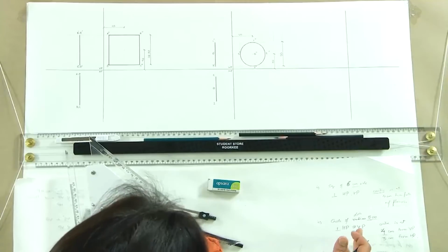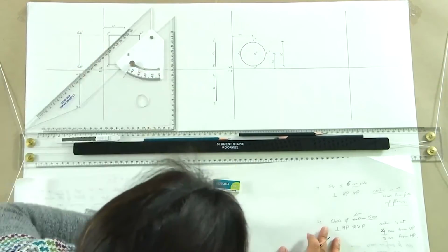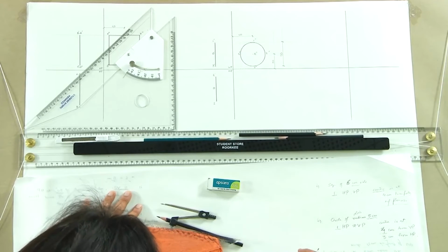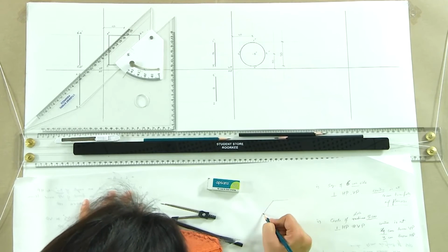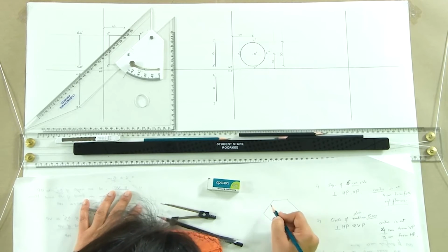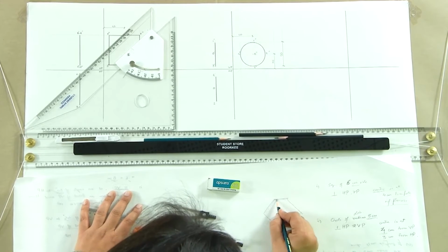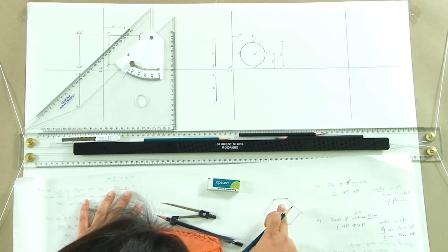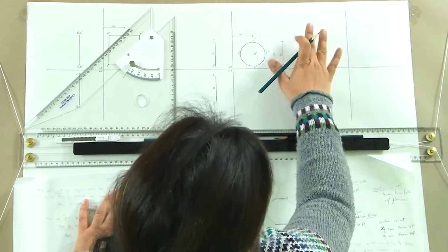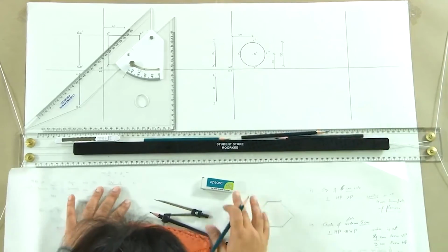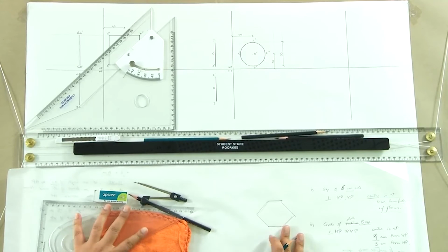Similarly, you could be drawing anything. Try drawing a hexagon which is perpendicular to both the reference planes and its 2 sides. So, when we are drawing a hexagon, 2 of its sides are parallel to HP. So, when you draw the hexagon, it will be lying like this in the side plane, because 2 of its sides are parallel to HP. So, you can start by drawing a hexagon in the side plane, and then you can have its projections drawn onto this. Just to give you, this is what you have to try at home.